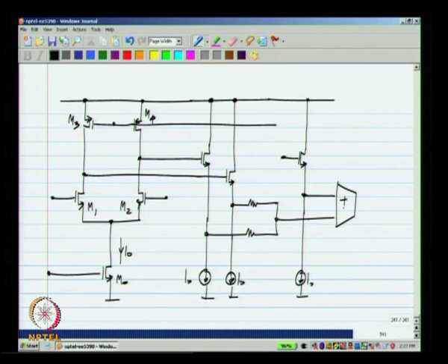And you use a transconductor to complete the feedback. Okay. Previously, I had used an op amp symbol here, but it is really a transconductor. You do not make a full fledged op amp in this case. Okay. It is really a transconductor because it has a high output resistance.